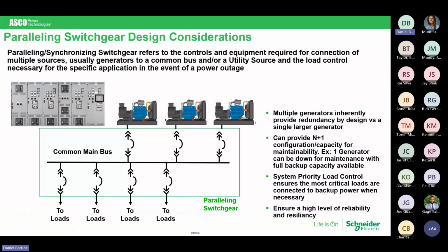Following up on what we did, we're going to look at paralleling switchgear. Now, I might repeat some things that you've heard previously, but in the case of traditional paralleling switchgear, as you can see, this is a 3-gen set lineup with a set of distribution. There's a master section. There are individual generator sections. We can do some other schemes to make it fit into your room better.